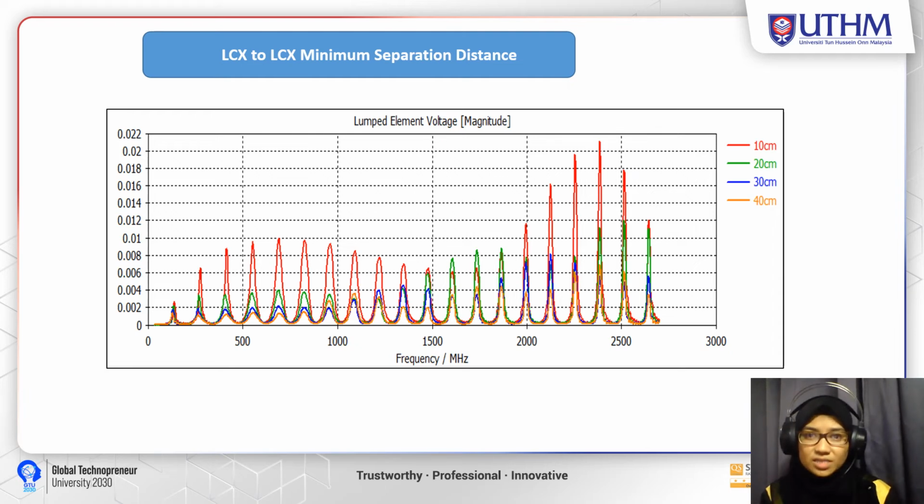From the simulation, the induced voltage at 0.3 meter distance between linking cables is 0.008 volt. Based on the result, the maximum induced voltage is close to that when the spacing is at 0.3 meter, as the spacing increases from 0.3 meter to 0.5 meter.